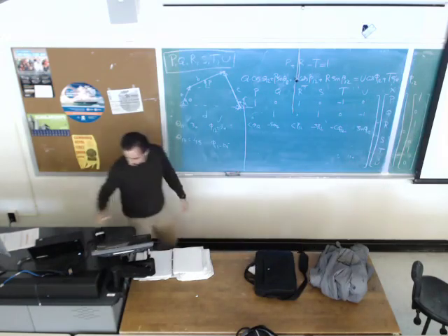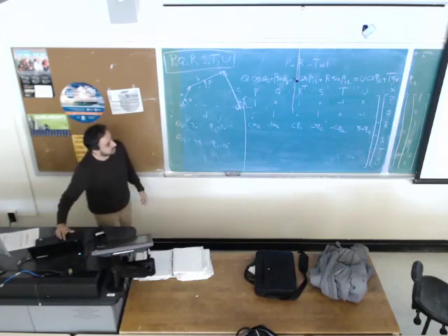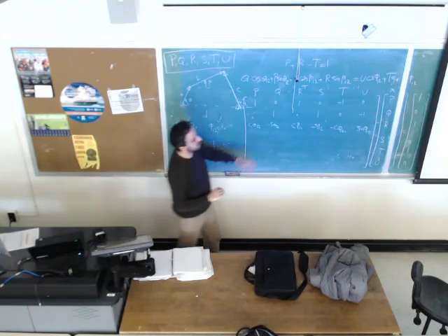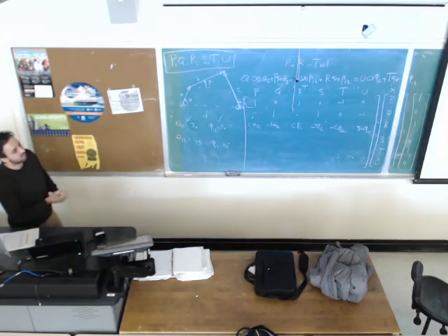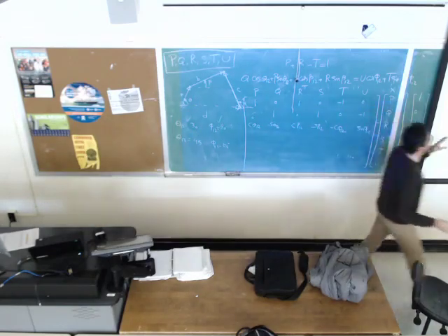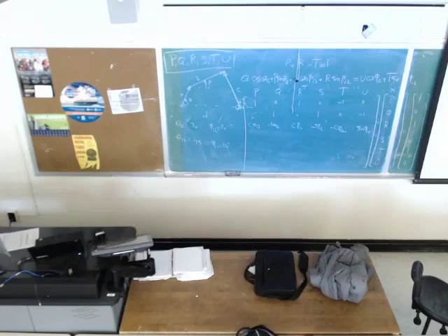1, 0, 1, 0, 1, 0, and the remaining terms should be written here. Now you are ready to solve this system of equations by using MATLAB or your calculator. These angles are given or known: beta 1 2 and beta 1 3 are two sources, and phi 1 2, phi 1 3, theta 1 2 and theta 1 3 are given. So you come out with P, Q, R, S, T, and U, but it's not what you are looking for.